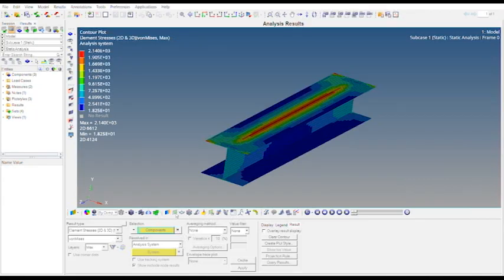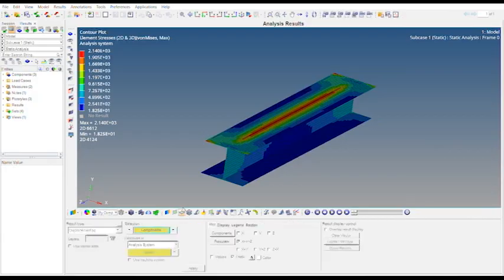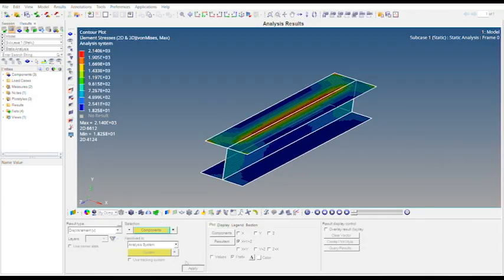So displacement is a vector and element stress is a tensor. In the vector panel we have all the vectors and can analyze them. In result type we only have displacement here, because displacement is the only vector in the result types we have requested. So we'll go to components again, click on displayed, and click on apply.